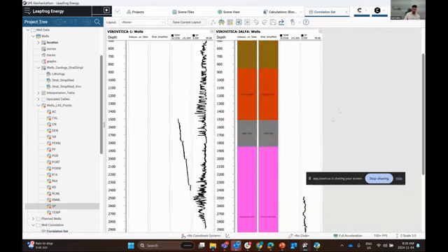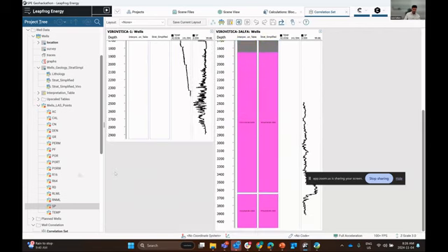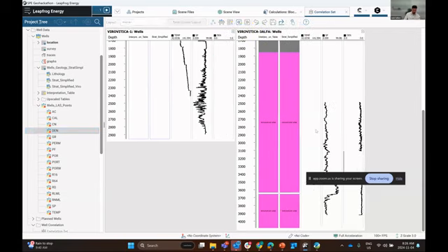And now based on the input data associated with our project, let's look at maybe density logs. So if you have a density log right here, and you have this particular interval, the interpretation table we can adjust to match any of the input logs, whereas the original strat simplified table we cannot adjust. So Leapfrog doesn't really like you to adjust the original raw data, but using this well correlation set, you can create a new interpretation table, which is essentially a new interpretation based on any kind of input, categorical or numeric information. Cool.